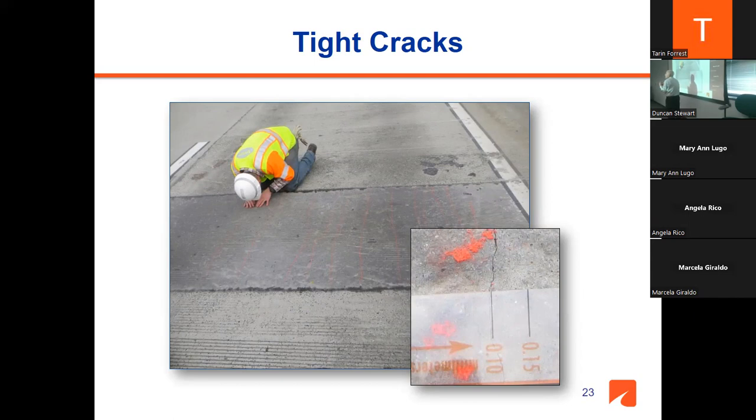So what is he looking for? He's looking for a crack. Oh, it's inspection. Yeah. No, he's trying to figure out the cracks and how wide those cracks are. But as you told him, the cracks are very tight. There are many of them, but they're very tight. You have to be on your knees to see them. And those kind of tight cracks don't let solutions penetrate. And that's our keeping dry concept.